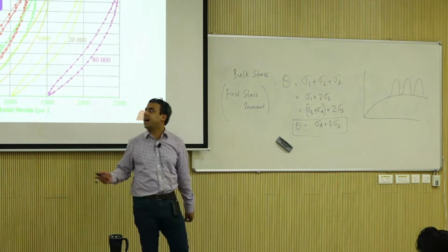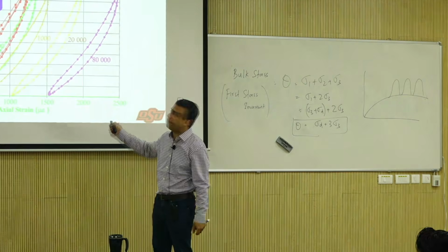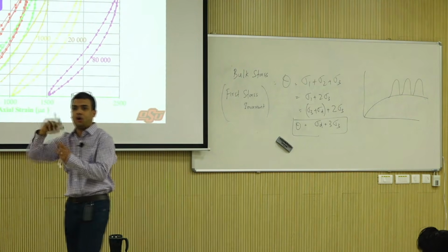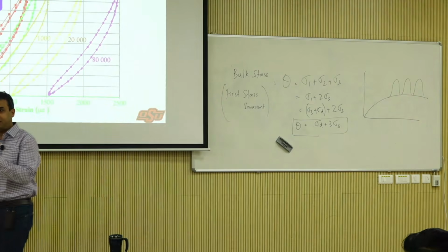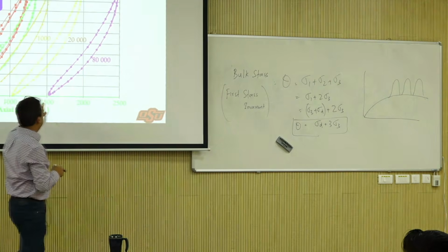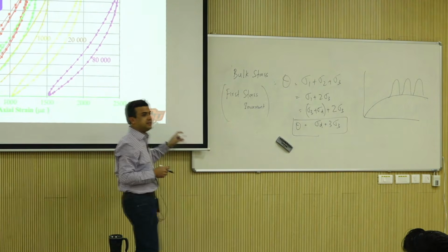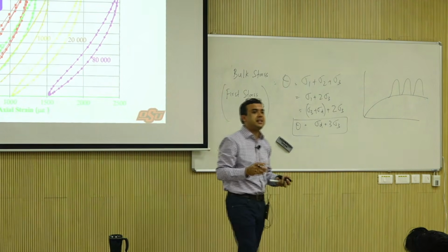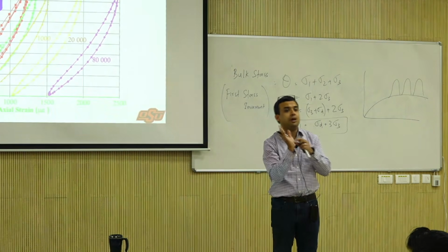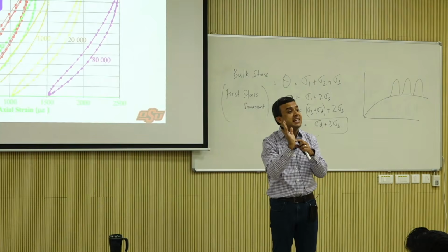Do you see how these shapes are concave up, like a saucer upward, not the traditional way of plotting? That is because for these materials, as the stress level increases, which is also as the strain level increases, the modulus actually increases.